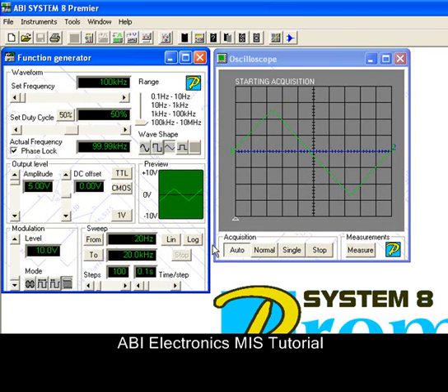The sweep function is a way of changing the frequency of the output signals automatically, from a start point to an end point. This transition can be done with a selectable number of steps with a particular duration per step. A linear transition or logarithmic transition can be used. You may observe the effects here.